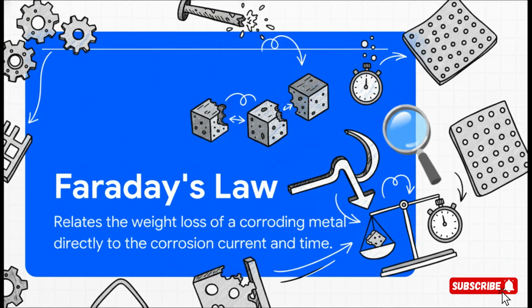This is not just some abstract formula, okay? This is the fundamental law that gives us a direct, predictable, mathematical link between that invisible flow of electricity and the very real physical loss of metal. It means that if you can measure the corrosion current, Faraday's law lets you calculate exactly how much weight in metal is being lost over any period of time.